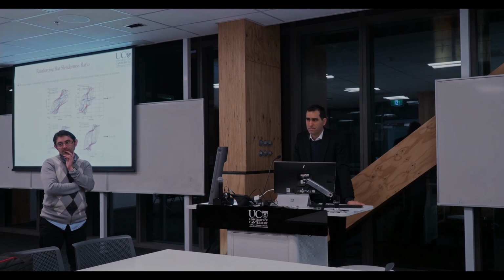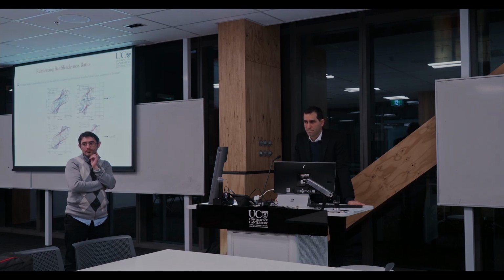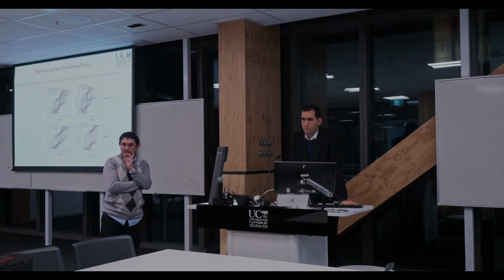So that is inherently there: once you have the spacing very close, it ticks off that criterion. But what if your intermediate bar is actually pulled out and you get your buckling within a longer length between 3 stirrups, right? In that case, for buckling, your section is as good as not having those 2 stirrups. That's the mismatch. When there is enough well-arranged stirrup, you get similar performance. But the fiber model, especially using LSR, which is a measure of ductile detailing in the truest sense, right? So that is it. Thank you, Rajesh.